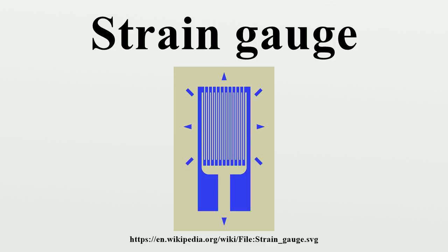Humidity. If the wires connecting the strain gauge to the signal conditioner are not protected against humidity, such as bare wire, corrosion can occur, leading to parasitic resistance. This can allow currents to flow between the wires and the substrate to which the strain gauge is glued, or between the two wires directly, introducing an error which competes with the current flowing through the strain gauge.